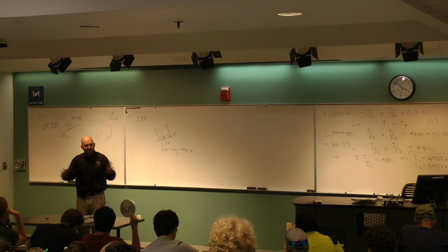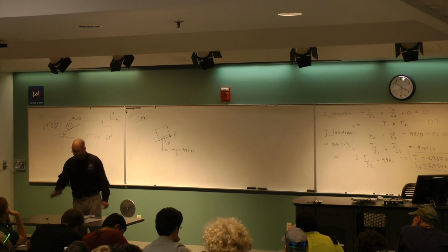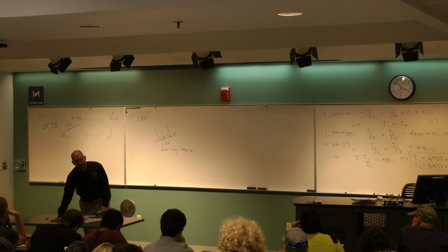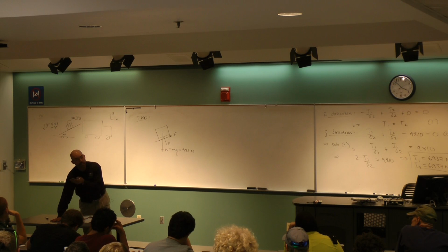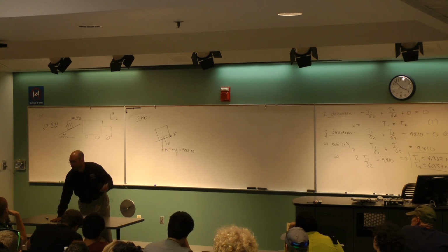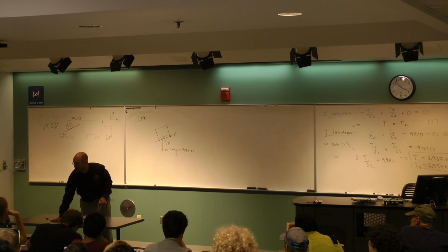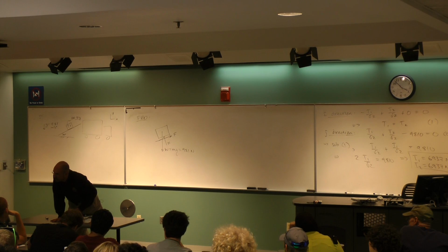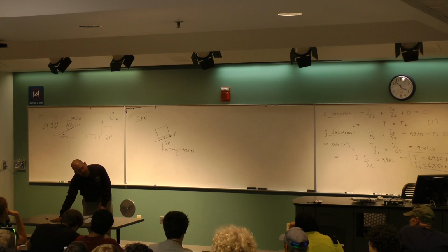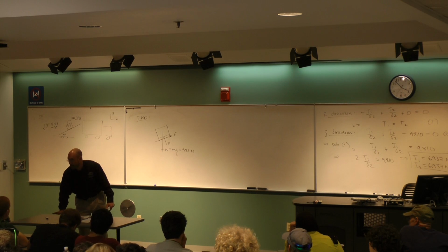Look, when two objects are in contact, there's only two ways they can interact. I'm leaning on the desk. Clearly, I'm putting pressure on the desk with my hand, and the desk is putting pressure back on my hand. This isn't high school physics, this is like 6th grade. The object acted upon gets a reaction. Newton's law: the desk pushes back on the hand as I push on the desk. If I am straight normal to the desk, everything is straight up and down. If I do it at an angle, it's still not moving. So I'm going to have a combination of two things: a force that's normal and a force that opposes sliding. That's the only thing my hand can do.